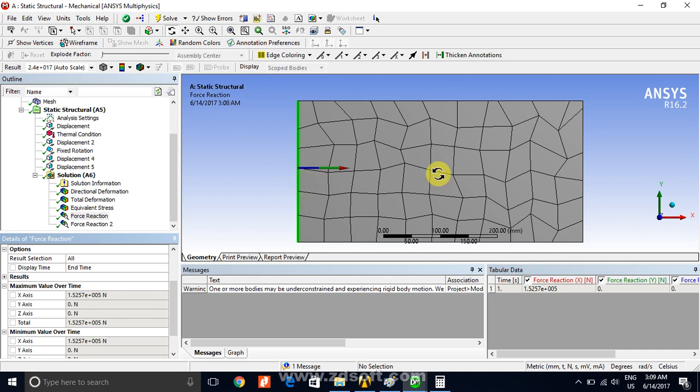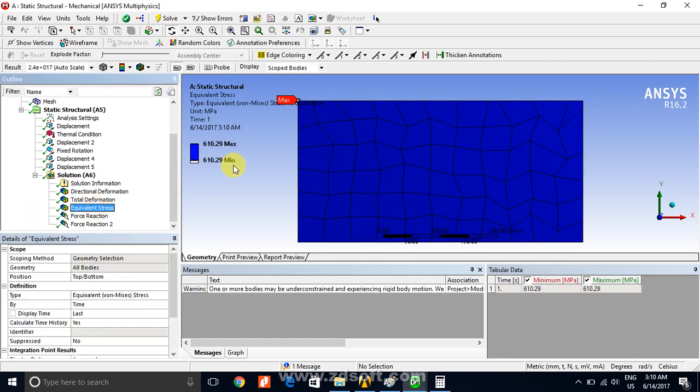So here sigma x, and this is my y and sigma y. So we calculate sigma x and sigma y due to this Fx and Fy, and these are the biaxial stress state. So sigma x and sigma y will become sigma 1 and sigma 2, the principal stresses, and because this is the von Mises stress, it is actually the equivalent stress, meaning square root of half of (sigma 1 minus sigma 2) whole square plus (sigma 2 minus sigma 3) whole square plus (sigma 3 minus sigma 1) whole square. It is actually this value.